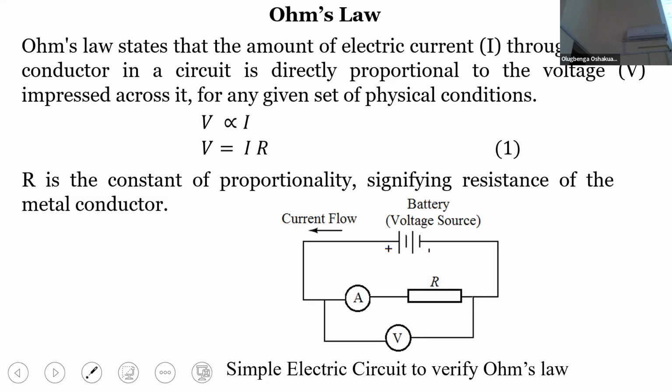Okay, I've heard two different answers. The 60-watt bulb offers higher resistance. That is why low current will flow through, while the 100-watt bulb offers lower resistance, allowing larger currents to flow through. So the 60-watt bulb has a higher resistance than the 100-watt bulb, but larger currents will flow through that 100-watt bulb than the 60-watt.